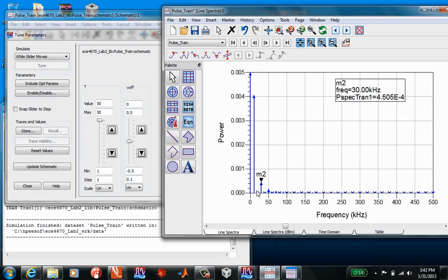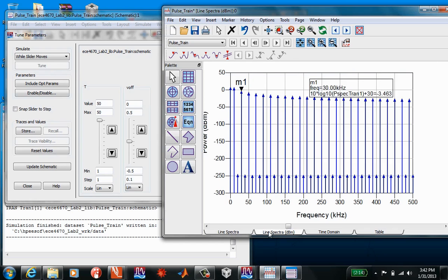So the first null of the sinc function occurs right at the second harmonic, then the sinc function comes back up here at the third, nulls the fourth, comes up at the fifth, and so on. Go on the dB scale where it's easier to see, but maybe a little bit confusing. That is essentially 0. Minus 250 dB is like down there, tiny, tiny, tiny.